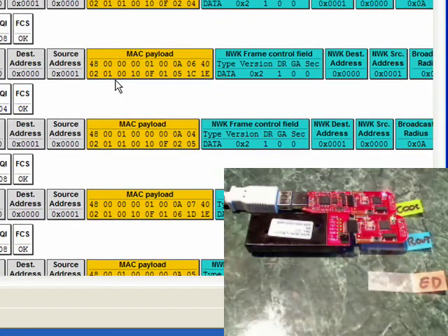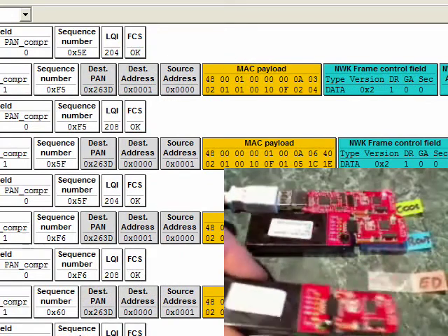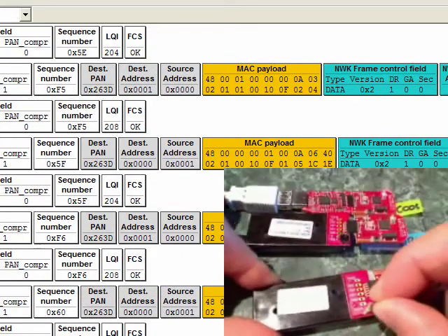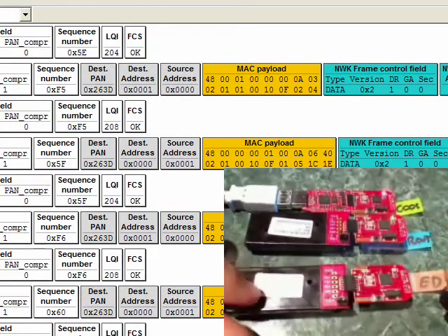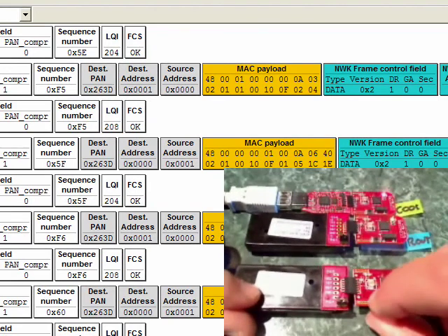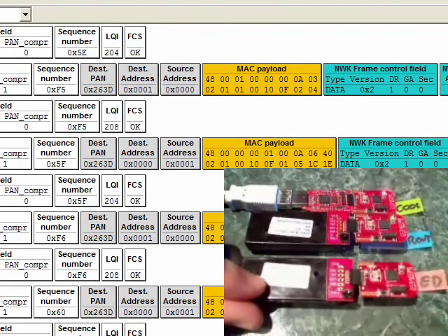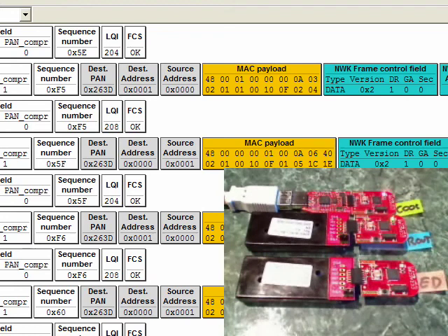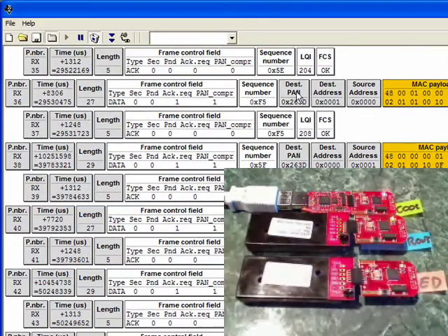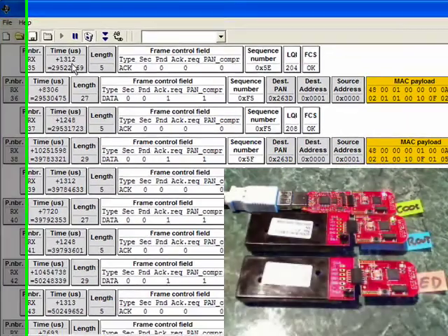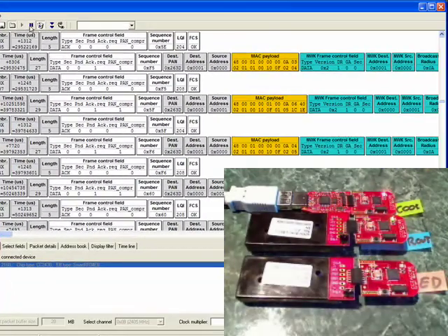Now we'll go ahead and try to get the end device to join up. I'll power that device up. Press the button twice. After a few moments, we should see the LEDs here just start to flash. Now they're flashing. Alright. I will stop the packet sniffer from capturing, and slide down.